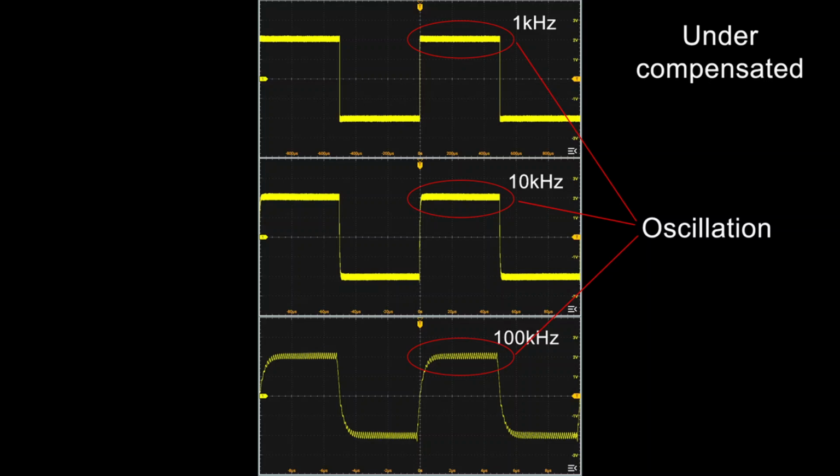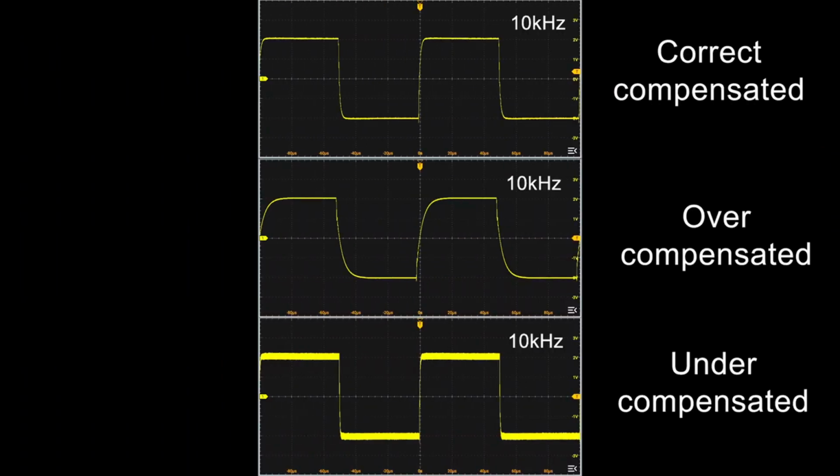We have to remind ourselves that in amplifier design, the top design goal is always to avoid instability from occurring to an amplifier. For comparison purpose, we gather together 3 10 kHz square wave responses. It is clear that when correct compensation is used, the amplifier produces very nice square waveform.